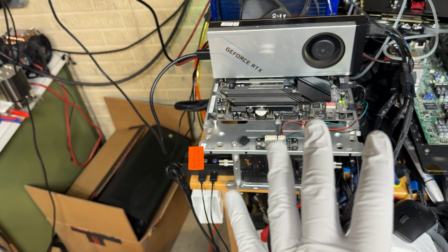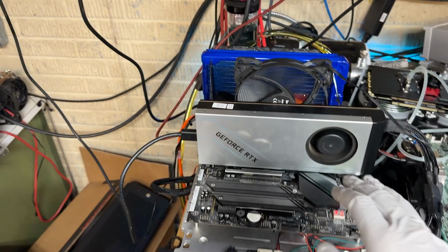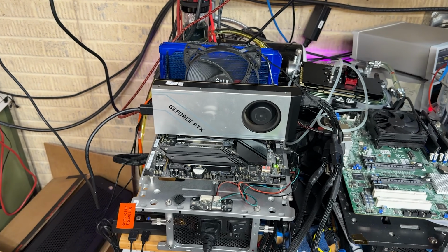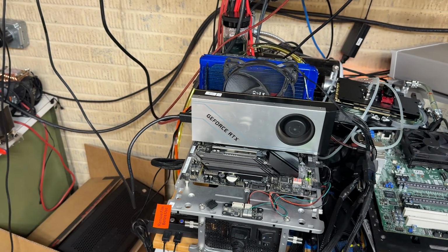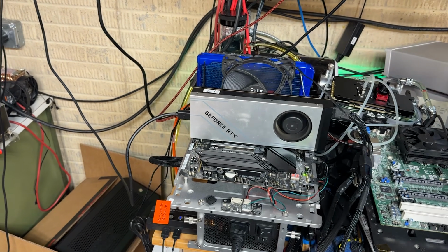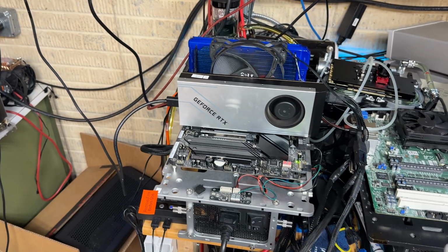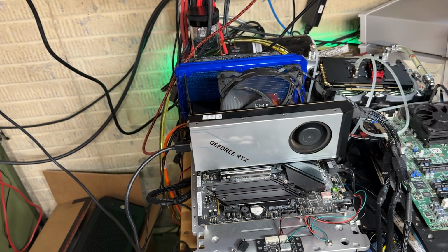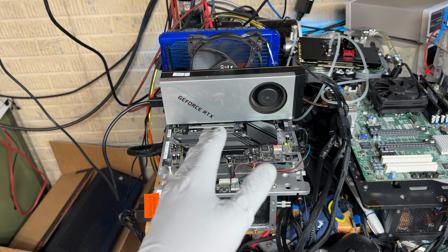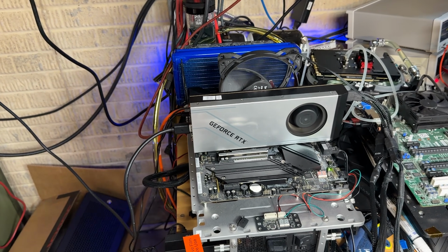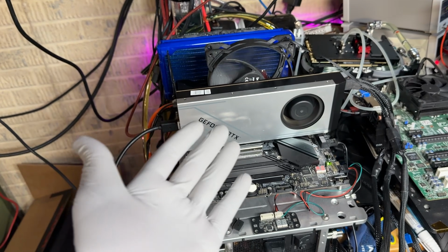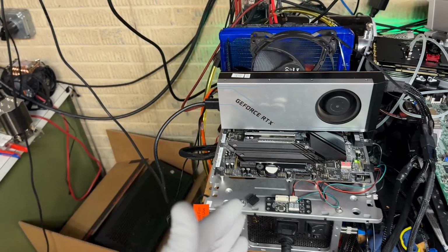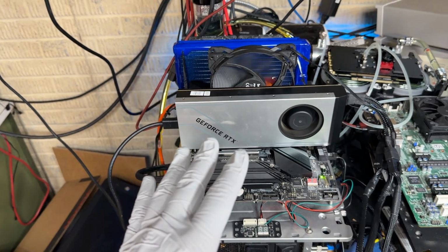So this is something I've not really run into, and this isn't a card that I've made myself. What I noticed is that when this came from China, all the memory modules were completely donor, so they were imported from another bunch of cards, and they're presumably tested. So the one thing I did see on this card was that when I was reworking it, replacing what I thought were the bad memory modules, everything was applied with lead-free solder. Lead-free solder has a higher melting point and a higher brittle factor, so it's more susceptible to solder ball cracks.